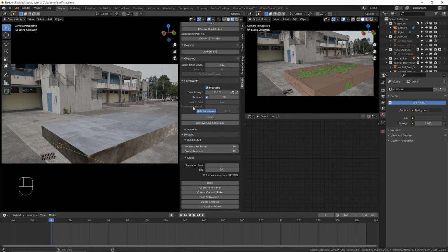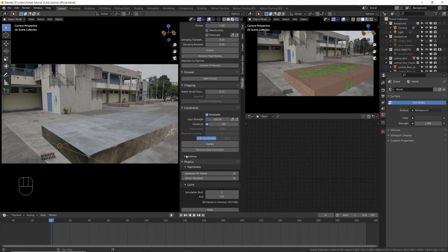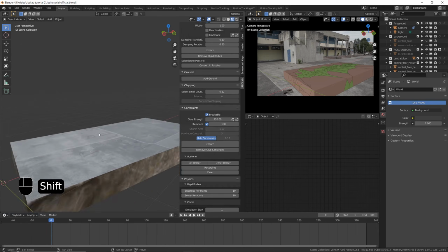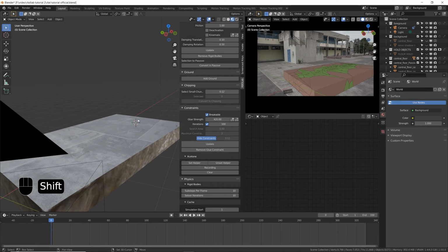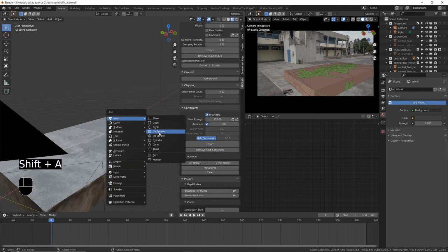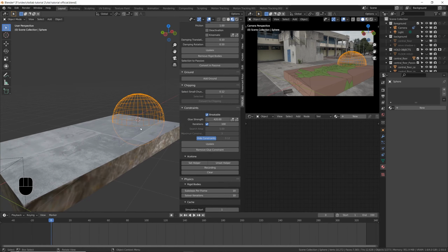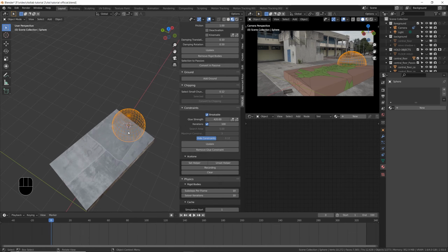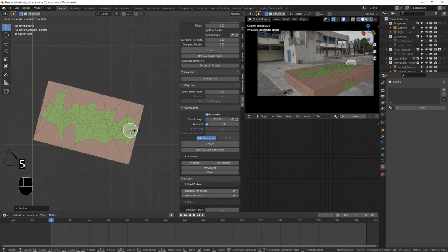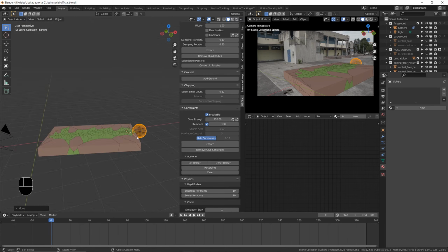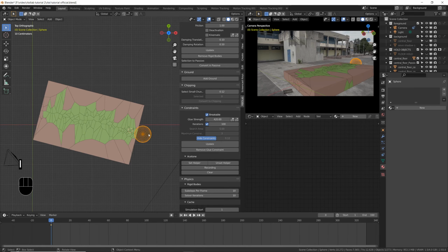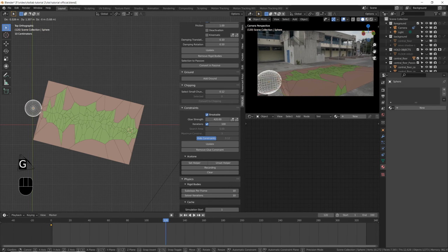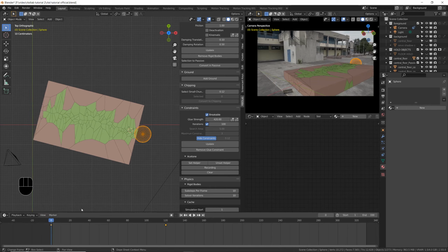What we're gonna do is add a helper, an object that breaks the connection between the rigid bodies. So I'm gonna go here and find, under here, the add-on menu. You will first have to create an object that is gonna act like a helper. So I'm gonna create a sphere, and I'm gonna click on set helper. But before recording it, we have to make some animation for this. I'm gonna make it smaller. I'm gonna put it here, and I'm gonna press I, location, and then I'm gonna go here to frame 120. I'm gonna put this here, pressing I, location, and see the movement.